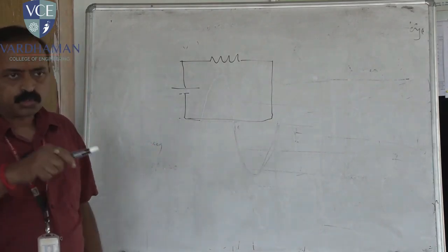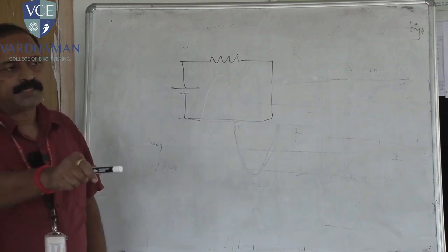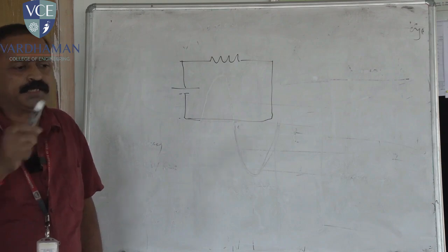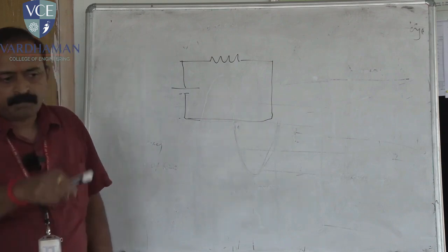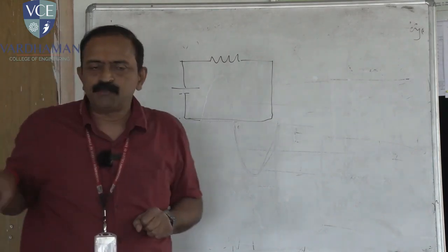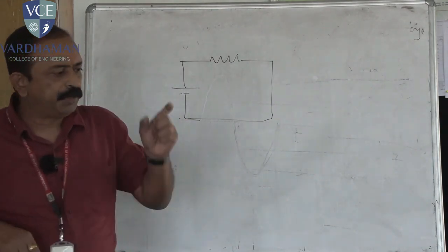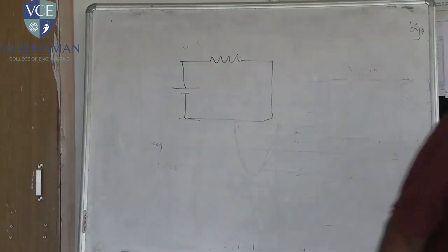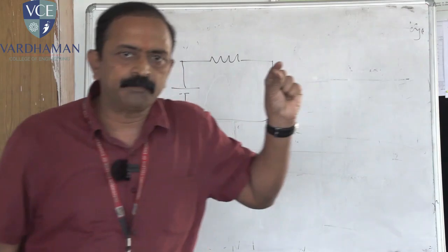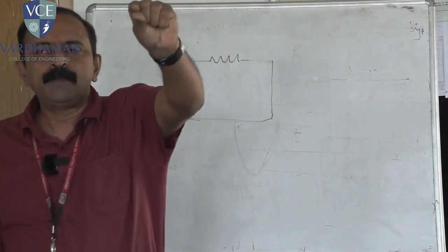Anyhow, we have taken utmost care in the laboratory by installing rubber mattings which are tested for 440 volts, ISO tested, Indian Standard Organization tested. Everyone should stand on the rubber mat and do the experiment. And this laboratory is well earthed. Earthing means the earth potential is 0. We have taken all the metal parts, and from the earth terminal, we have taken a GI wire, galvanized iron wire, which is a good conductor for electricity, and buried it into the pit.